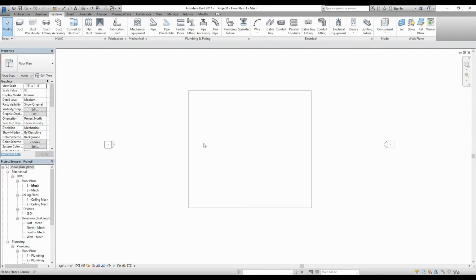This is video 3 of the Revit for the MEP Professional series. In this video we'll focus on drawing duct. Now drawing duct is pretty similar to drawing pipe: you have the two clicks. You click to start the duct and then you click to end it. As with pipe, you have similar fittings that you use for duct.